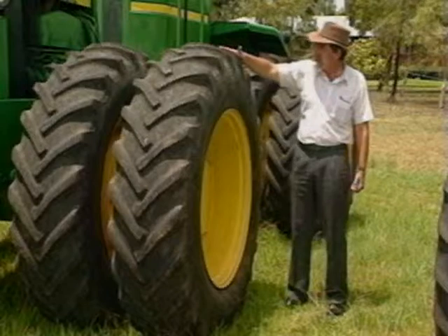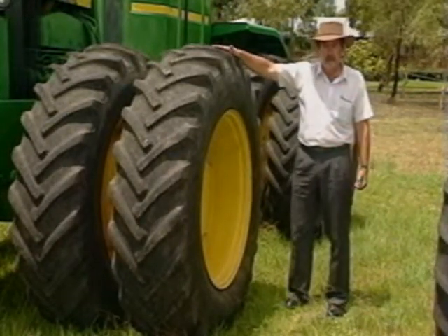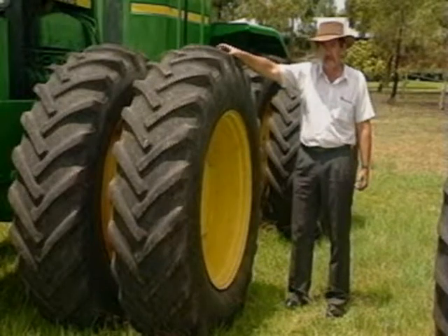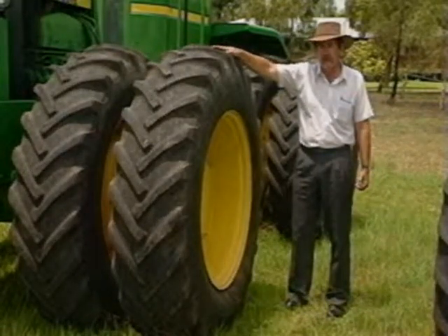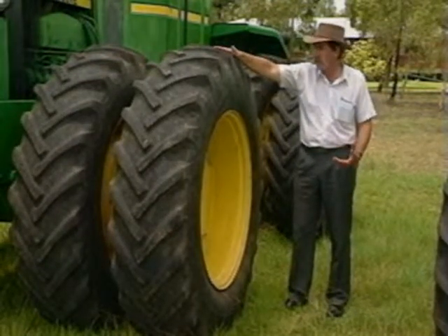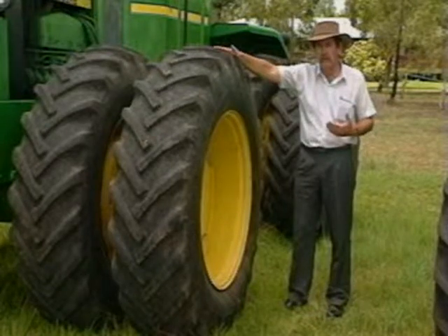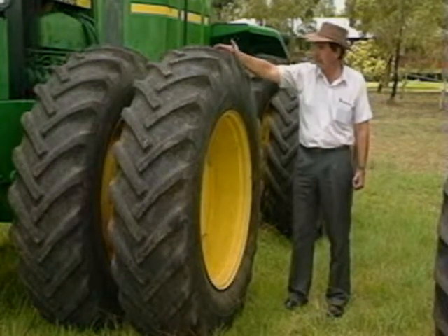Well, then we get down to a situation where the tyre appears to settle down. And this is normally in the region of about 25 millimetres of rubber remaining, and we find we generate the best levels of traction at that height because there's less movement of the lug in the soil, and the tyre wear seems to settle down, or appears to settle down, and the tyre runs out its life.